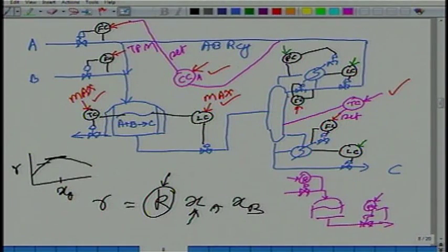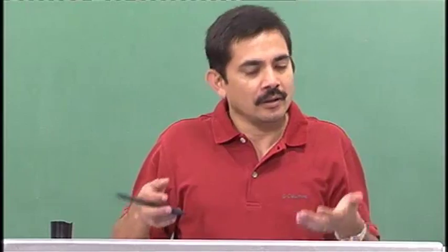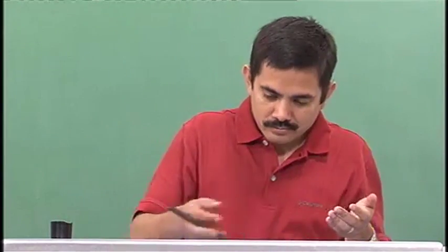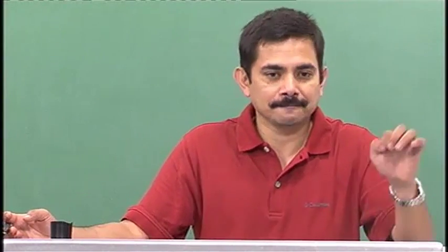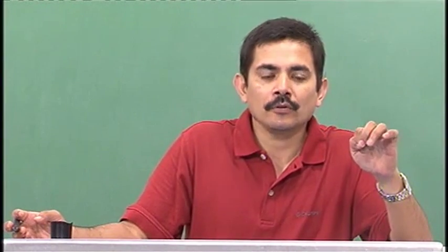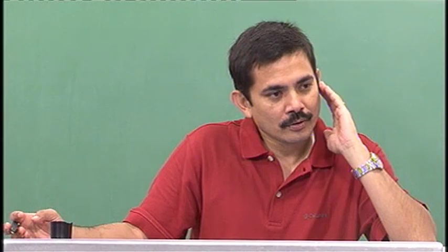Yes or no? Just like in a tank, the level is non-self-regulatory, so the control system must regulate the level, so you put in a level controller. Component inventory is non-self-regulatory, so it must be regulated, it must be controlled. If your control system is not doing that, you have put in place a control system that is bound to fail, and it is failing because of what?